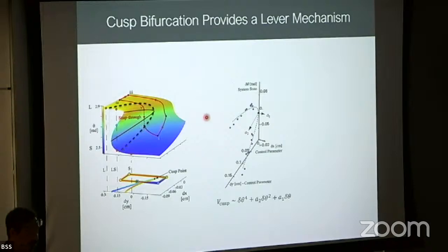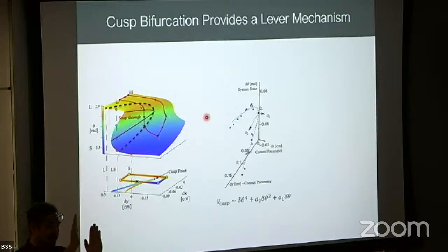What you're doing is you're changing the XY panel's position, this panel's position relative to this one. And you have a particular magnetic pattern so that when you sum all these up, you end up getting an equilibrium surface with this thing either closed or open. So in some sense, if I have a magnet here that's attracted to this one, if I move this one down and this one is repulsive, it'll want to open up. That's mechanistically what's going on. You're changing the surface that this one is seeing by moving this in X and Y.